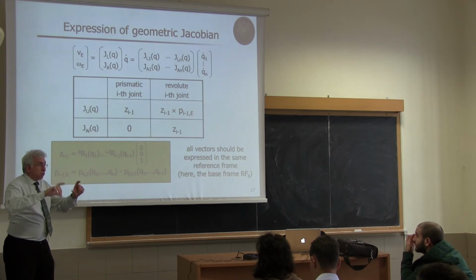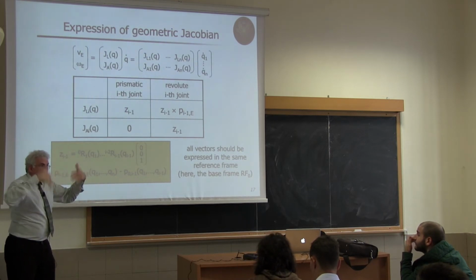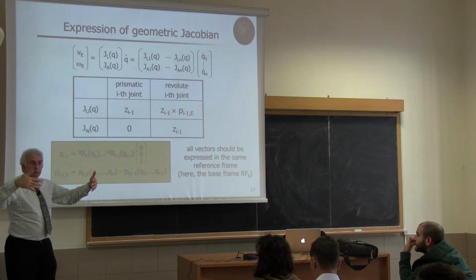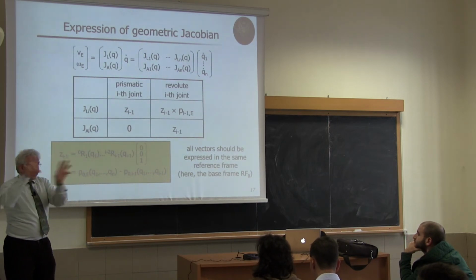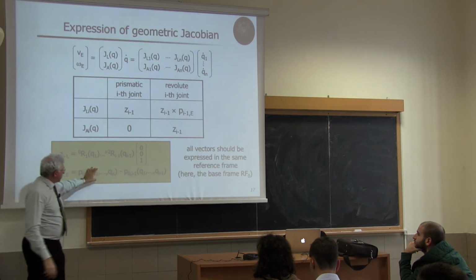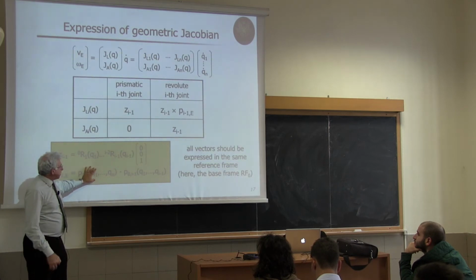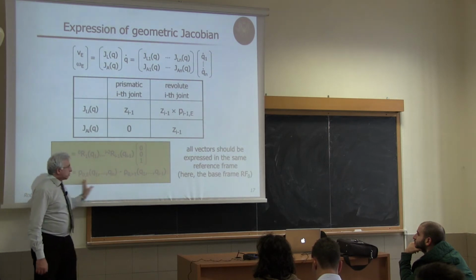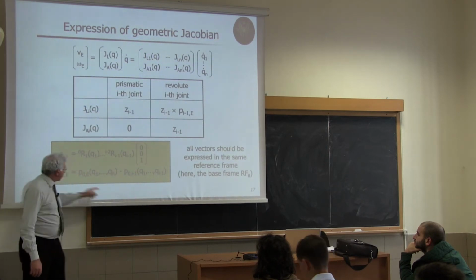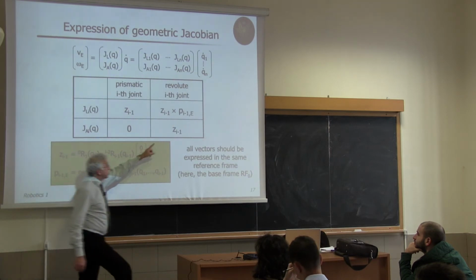And how do I compute this? By multiplying 4x4 homogeneous Denavit-Hartenberg matrices and then extracting the last column, removing the 1 of the 4th row and then making the difference. So I have an expression as a function of q, which I replace in this vector here.